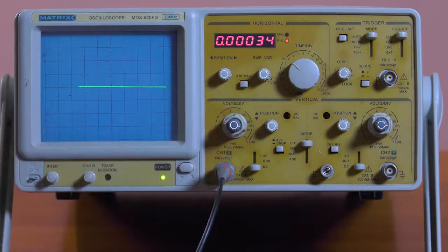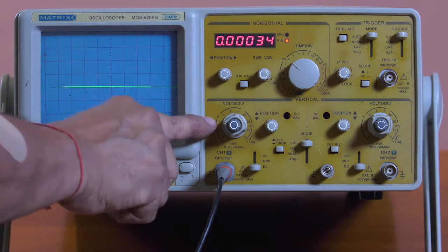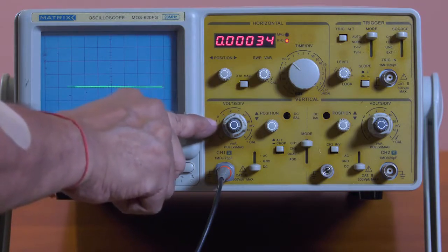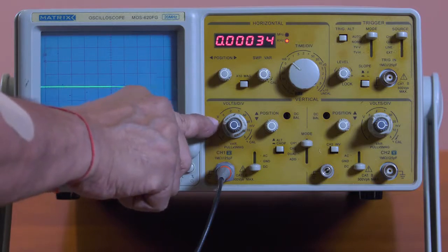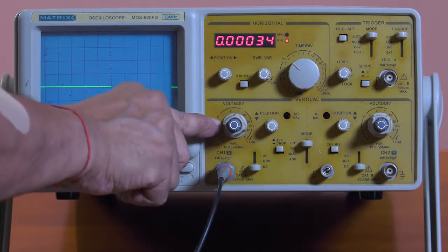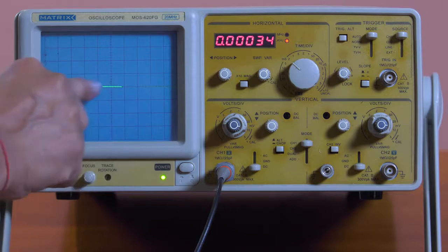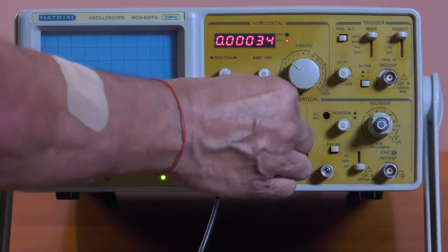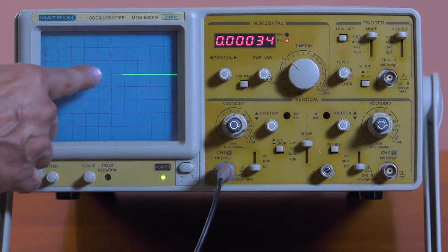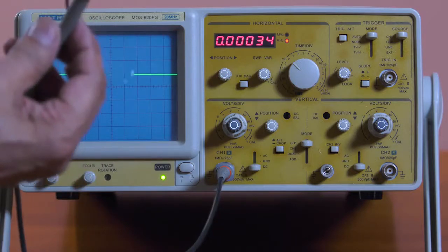I want to set it on 1. What does that mean? It means that if I get a reading, I must look at this number and see where it is set. This tells us it's 1 volt per division. So if this trace goes up there when I'm doing my measurement, it means that it's 1 volt, not forgetting that you have to multiply it by 10, like we explained.